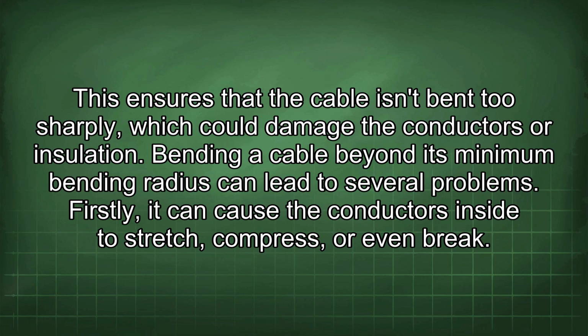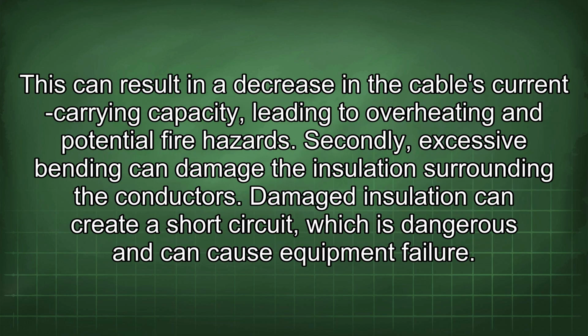Bending a cable beyond its minimum bending radius can lead to several problems. Firstly, it can cause the conductors inside to stretch, compress, or even break. This can result in a decrease in the cable's current carrying capacity, leading to overheating and potential fire hazards. Secondly, excessive bending can damage the insulation surrounding the conductors. Damaged insulation can create a short circuit, which is dangerous and can cause equipment failure.